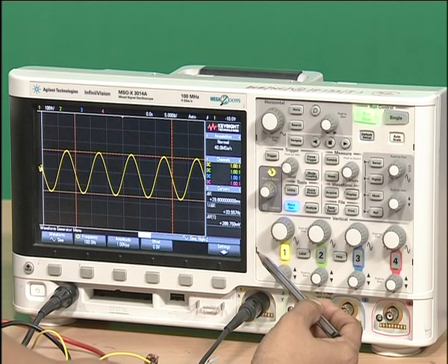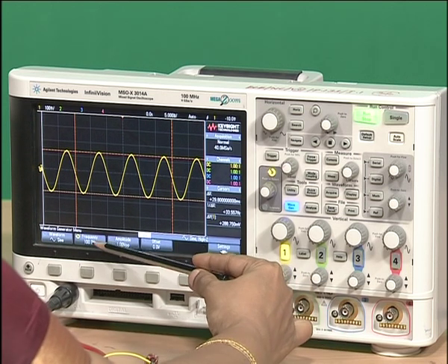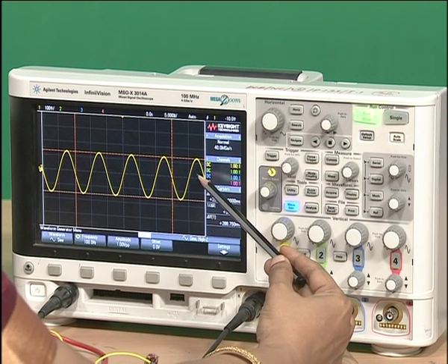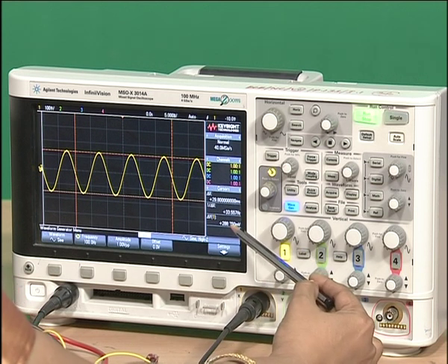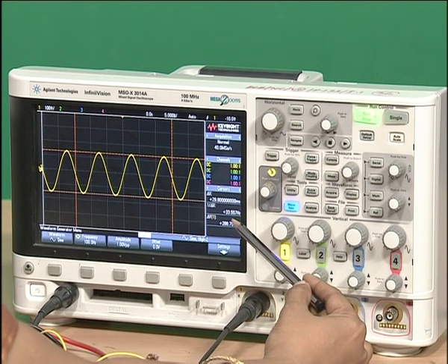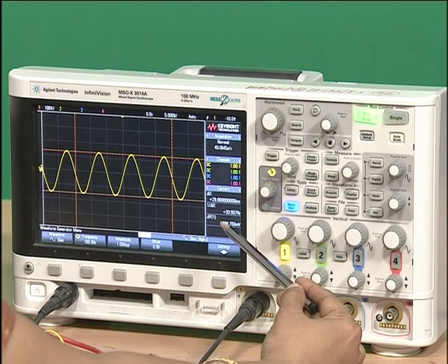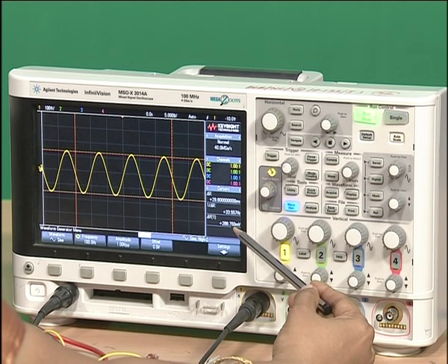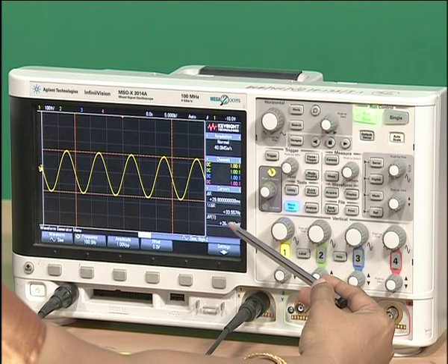Now, 1 decade away from the cutoff frequency, this is at 100 hertz now, the input signal frequency is set to 100 hertz. The output signal is observed. The peak to peak amplitude is now 288 millivolts. The corresponding decibels is minus 10.8 dB. Now, if you compare from the cutoff frequency, it is about 14 dB down. Since the reading that is taken now is closer to cutoff frequency, there is a deviation from the expected. The expected is about 20 dB per decade roll off. Now, the reading is taken closer to cutoff, so that is why there is a variation here.